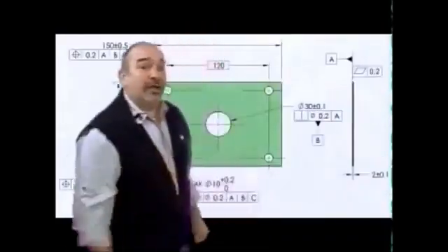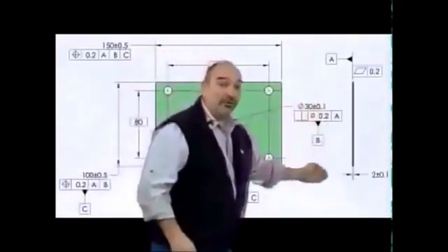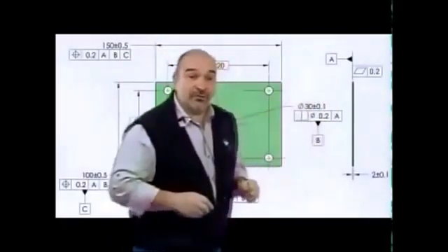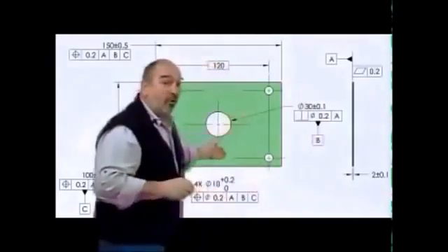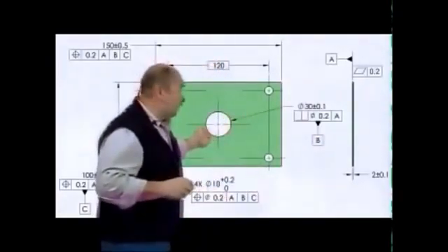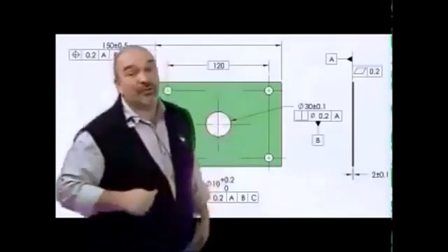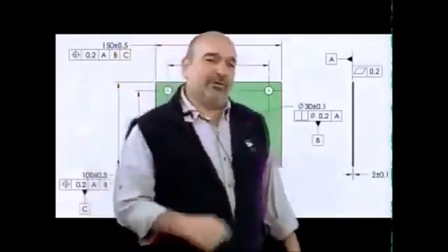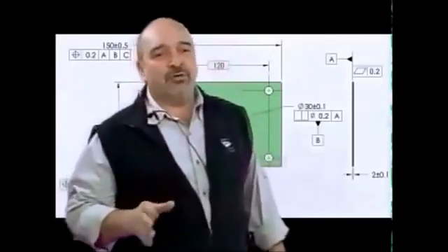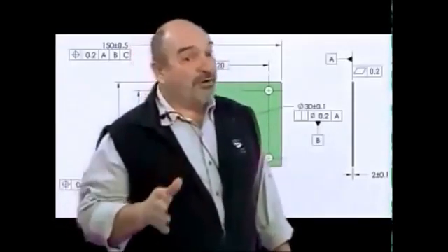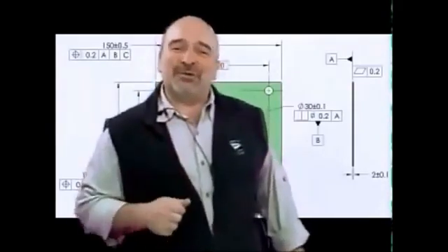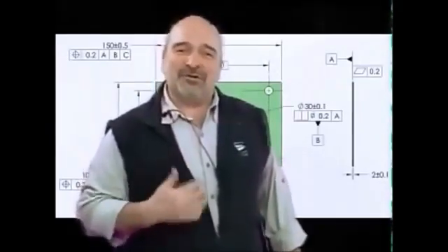Now the second drawing has a large flat surface as a primary datum feature. It can arrest 3 degrees of freedom. The center hole then is your secondary datum feature, and now it only has to take away 2 degrees of freedom, which it can reproducibly do. The datum features you pick have to be usable. By selecting practical datum features, your designs will perform better, and you can let everyone know that you are a faithful reader of my tips.